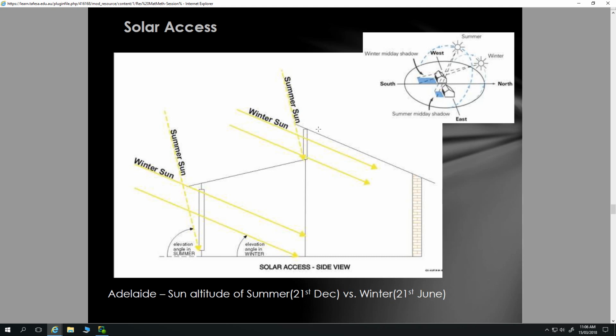That brings warmth, brings solar radiation, and that warmth is trapped within the house to a certain degree. But then in summertime, we have adequate eaves to ensure that when the sun is high in the sky, the eaves shade the windows entirely, so we don't get any sun onto those windows.